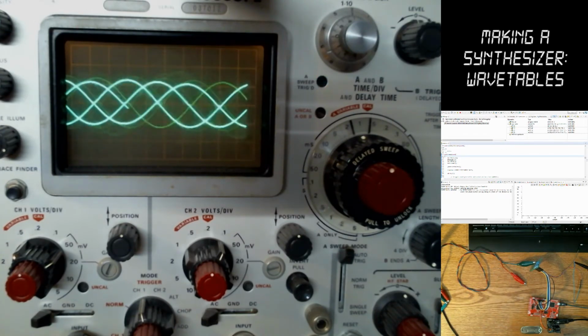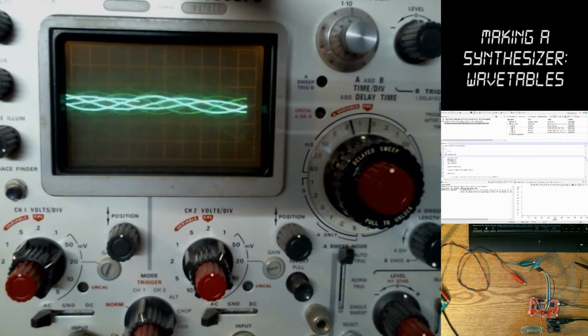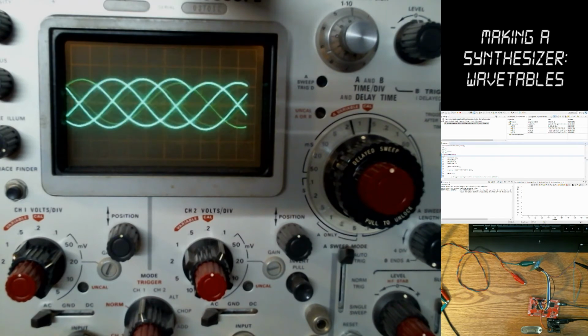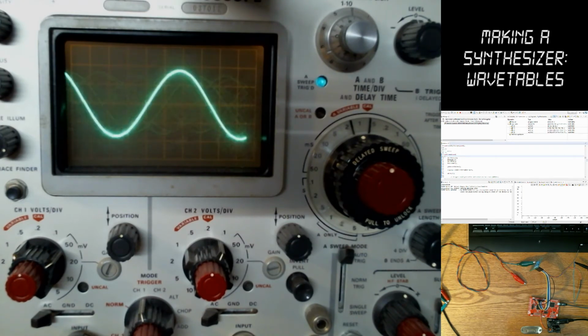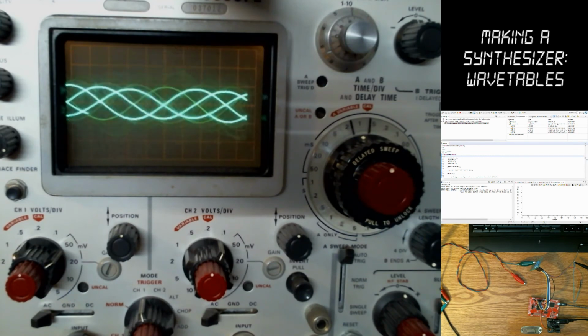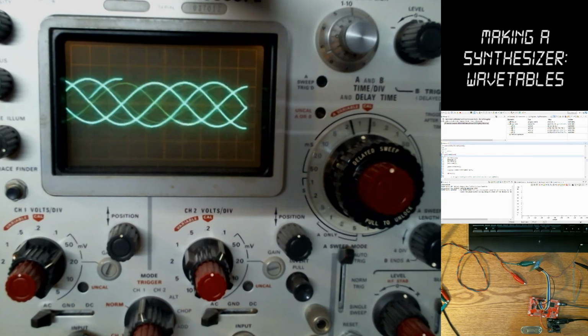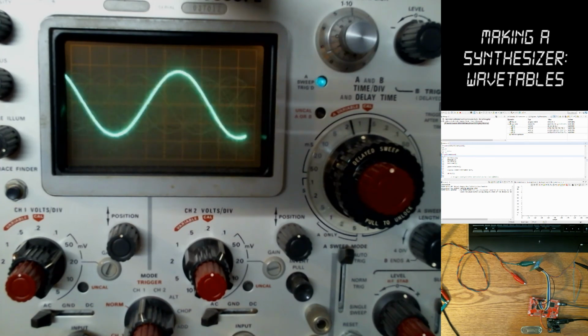Alright, so that's kind of what you can do with 2 oscillators, where one of them you can vary the pitch a little bit. But yeah, that's it. This is through an 8-bit DAC. It still looks pretty smooth. It'll turn out better when we add the reconstruction filter after it. Right now this is the raw output.